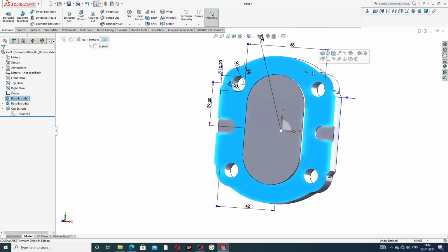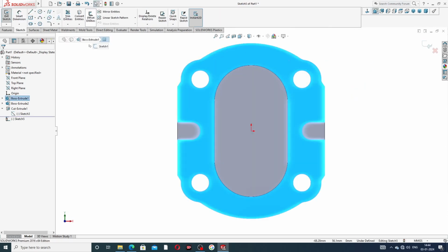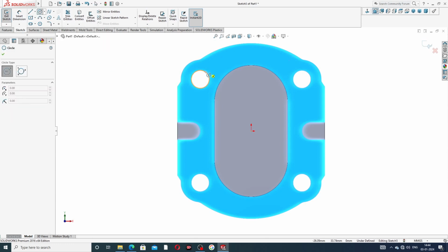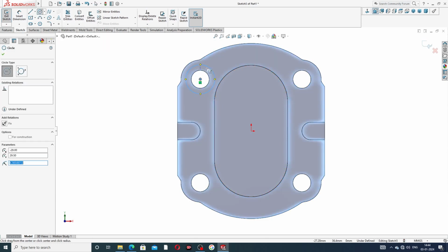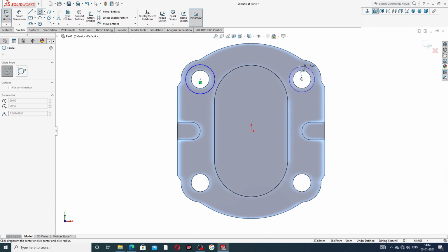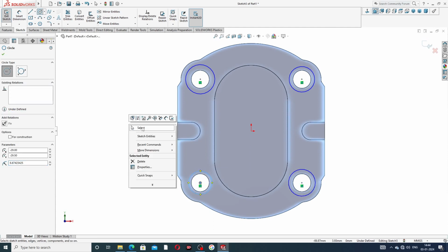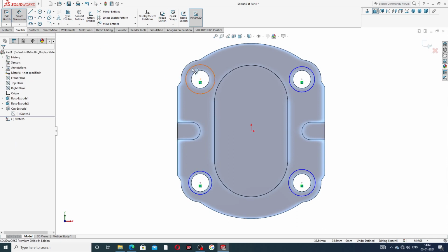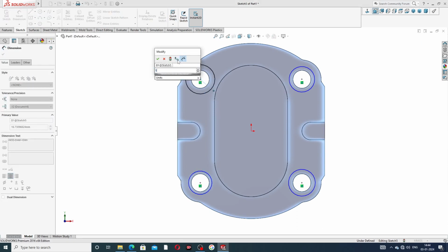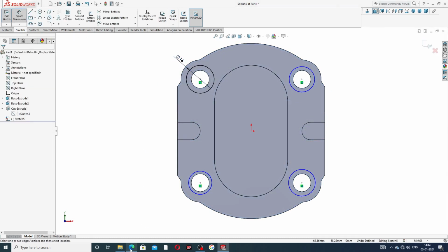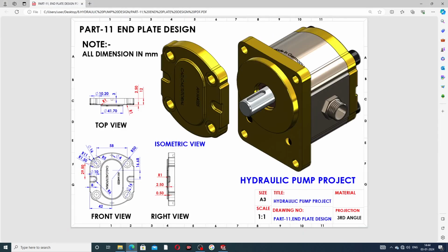And next is this face, sketch normal, drawing a circle. One by one on all the center points, draw a big circle here, and this dimension is 16 millimeter. Use this 16 millimeter for the cut out, with a thickness of 0.5 millimeter.